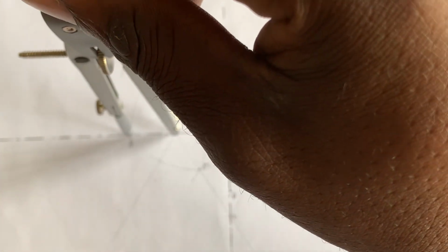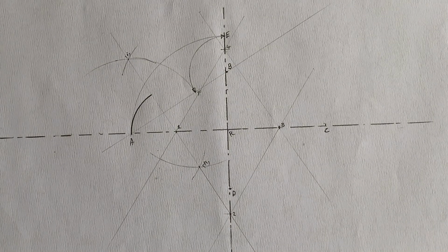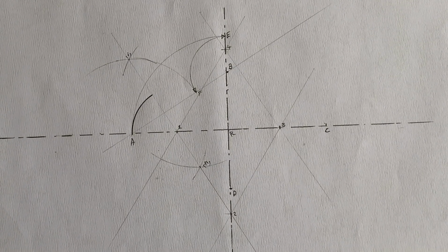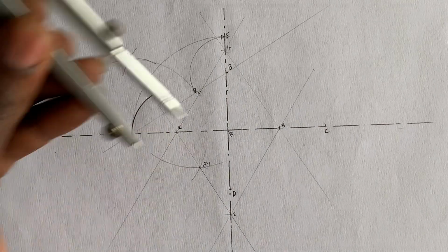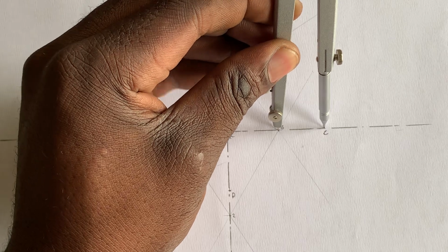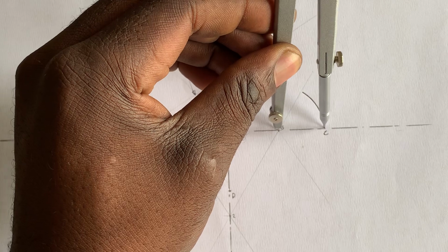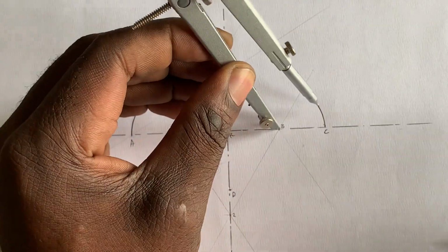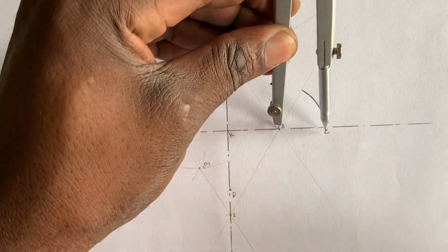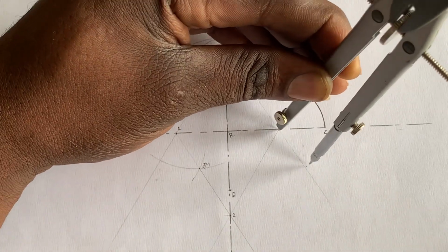So now I draw dark till the line of Roman figure 1 and Roman figure 2. It's the one that is guiding me where to stop. Now I come and do the other side, place it at 0.3, further extend it to C, then have it dark like this. If it was a full ellipse, we would go up until here. So it's not a full ellipse.